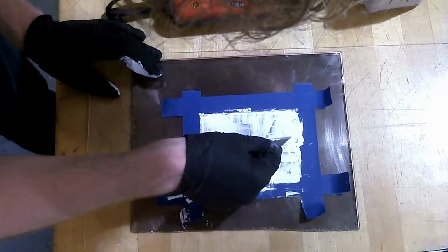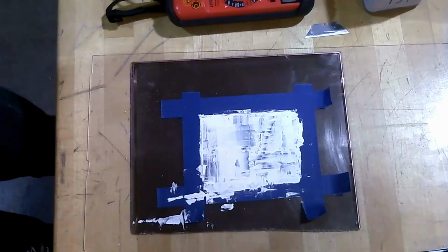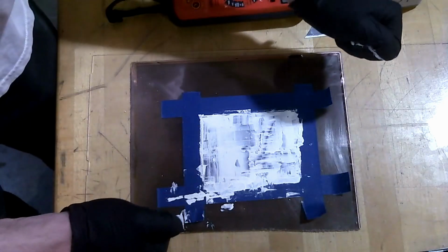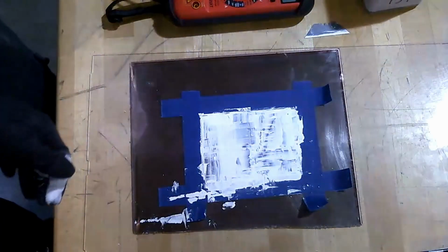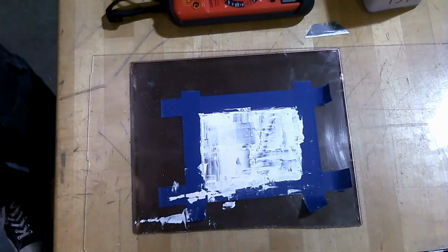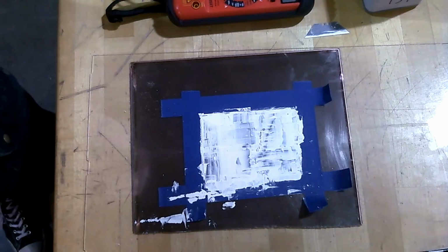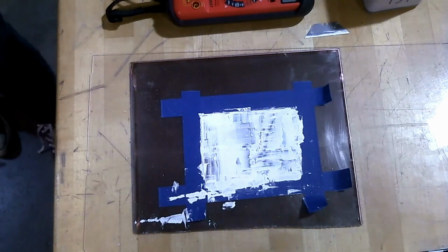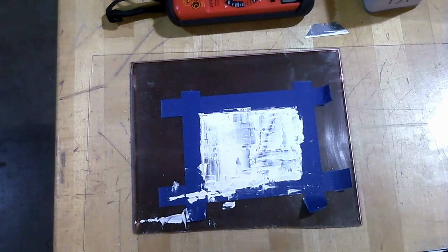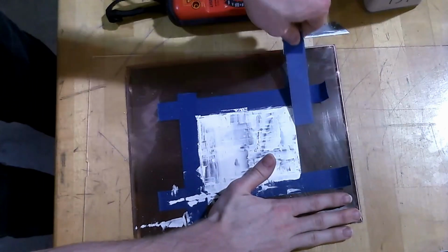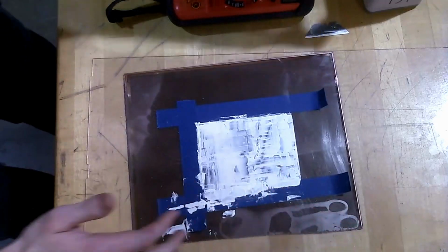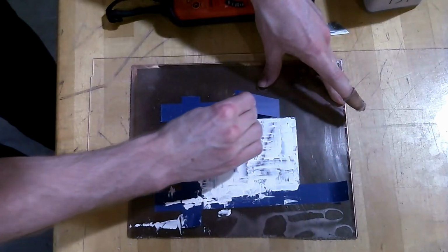Next, we are going to remove the tape and then proceed to sinter the titanium dioxide. I found that the best way to do this is in an oven. You have to get it all the way to 450 degrees Celsius, which is very hot. A lot of conventional regular ovens don't quite make it to that temperature. But I did have some success bringing it as high as it could possibly go in my common kitchen oven and using that, but it is not the optimal way to do it.